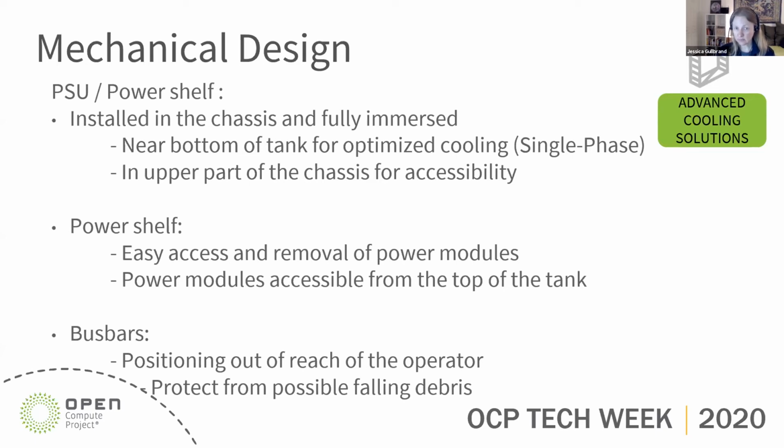This is true, as we said, for single phase, depending upon what the thermal requirements of those power supplies are. Or you can decide to install it in the upper part of the chassis for accessibility. So if it's something that the user or customer wants to be able to service often or have easy access to, you want to place it, of course, in the upper part of the chassis.